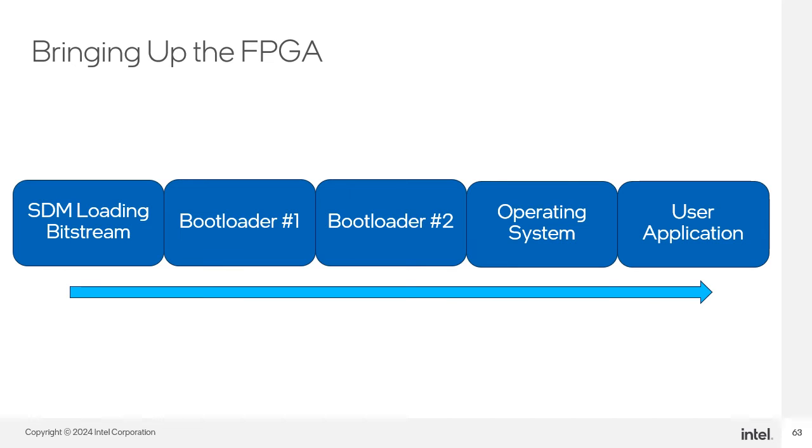The second stage bootloader is the second boot stage for the HPS. The first stage bootloader initiates the copy of the second stage bootloader to the HPS SDRAM. The second stage bootloader typically enables more advanced peripherals such as Ethernet and supports a command line interface. You can create the SSBL from U-Boot or the ARM Trusted Firmware, both of which are found on GitHub.